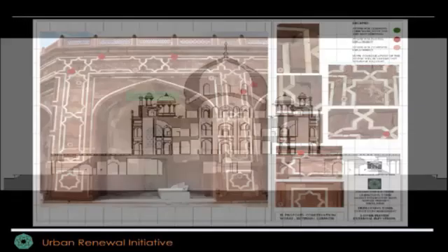So when the joints of the stone are filled up with cement, the cement is harder than the stone. So whatever water is coming down and bringing whatever salts with it sets off a deterioration process that cannot be reversed, because the water is then coming out of the sandstone, which is porous. It's a sedimentary rock. This was followed by a whole analysis of the structure.